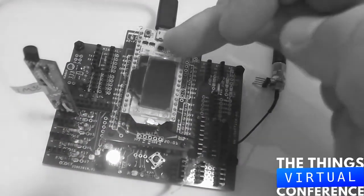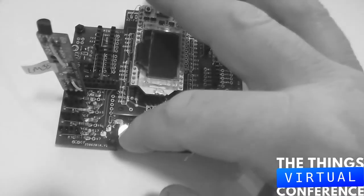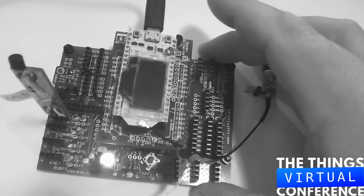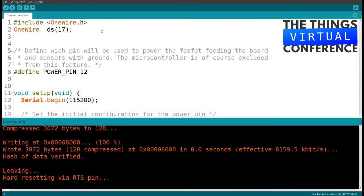The blinking here is the Heltec. It has a blinking LED if it runs. I can see there's power on this board down here. What do we do now? Can we see anything? Yes, we can, because in the Arduino IDE we can go to Tools, go down the menu to Serial Monitor and click there. Instead of using the mouse, you could also hold down, on Linux at least, Control Shift and push M. It would be the same. And we would see a serial monitor.